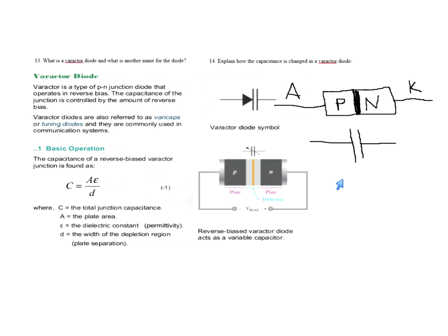You may remember a long time ago, all of the tuning knobs on the radio or the television, you had to grab and turn them. You were changing the capacitance. Today, what you have is a digital readout, or you just press a button, and what you're doing is you're actually changing the voltage on a diode that's reverse biased, a varactor diode. So a varactor diode is a kind of diode that is used as a capacitor. It's always wired reverse biased.